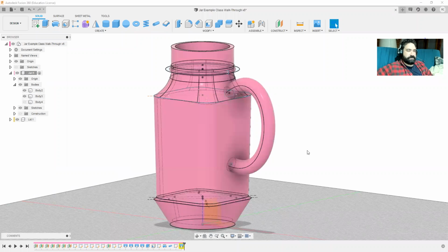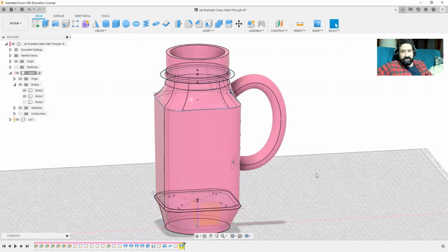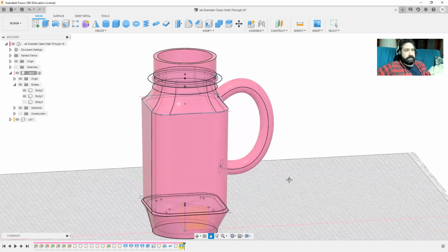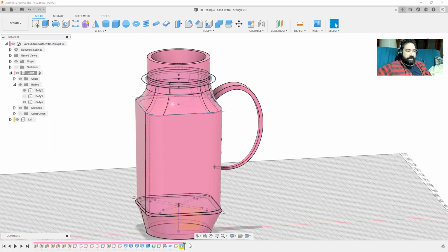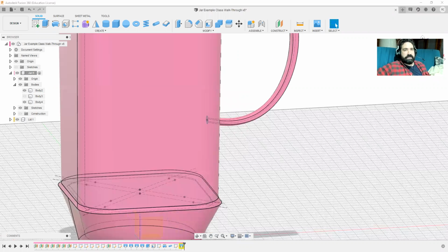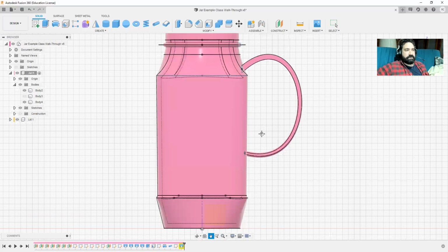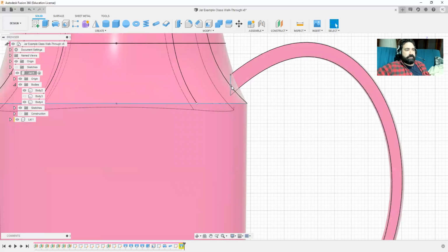All right, so a couple other things. First, we tried using the pipe tool to create just this standard handle. Honestly, that works fine. It will need a handle. That works perfectly well, but if you wanted something more specific to your design, we use the loft tool. Now I'm getting an error here. The reason I'm getting an error is one of the things we played with last week was with the pipe tool, we had to move the rail, the original sketch, internally, because if we didn't, that handle was going to be floating on the surface.